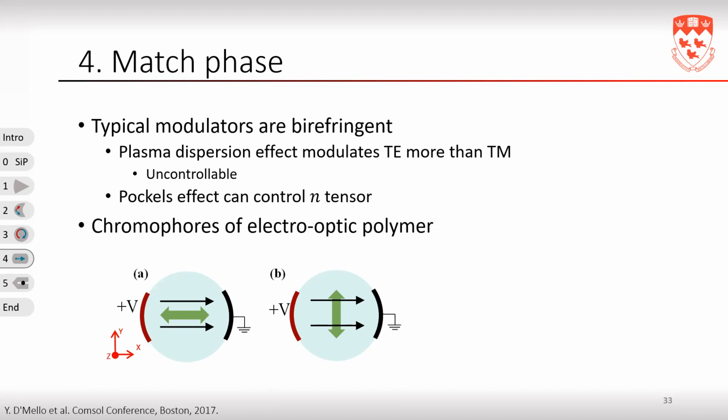Now, really simply, when an electric field is parallel to the plane of polarization, it induces a different phase delay than when it's perpendicular to the plane of polarization. And so I extended this concept to design a device that had 3 electrodes, 2 signals, and a common ground.